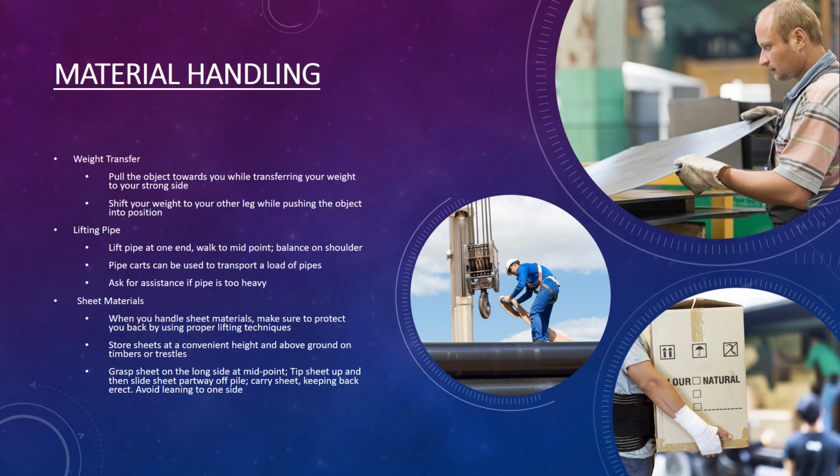Sheet materials. When you handle sheet materials, make sure to protect your back by using proper lifting techniques. Store sheets at a convenient height and above ground on timbers or trestles. Grasp sheet on the long side at midpoint. Tip sheet up and then slide sheet partway off pile. Carry sheet, keeping back erect. Avoid leaning to one side.